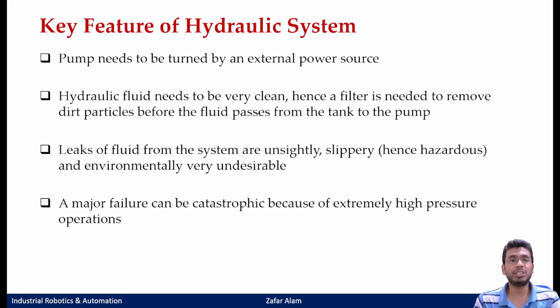Fine. So if you recapitulate the key features of a hydraulic system, there would be a pump. Why do you require a pump? Because that pump would be driven by an external source, that is the electric motor, to build the pressure in the system. Then you require a filter so that the fluid is clean and does not choke the system.